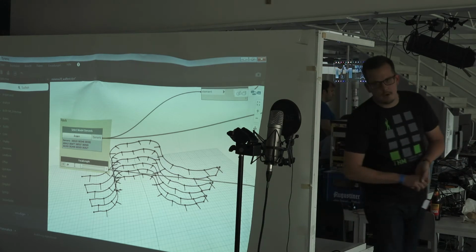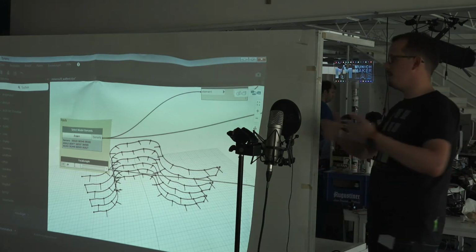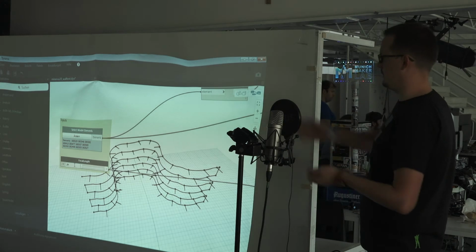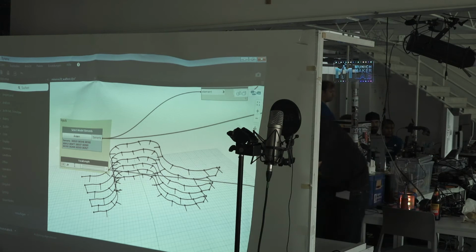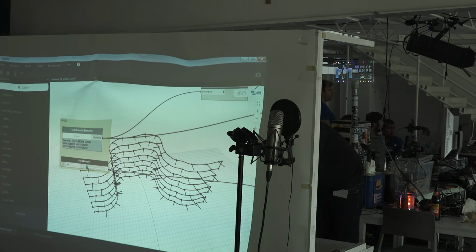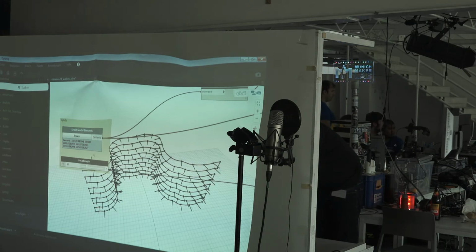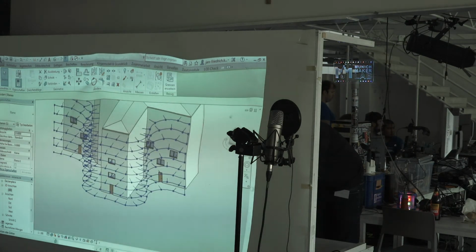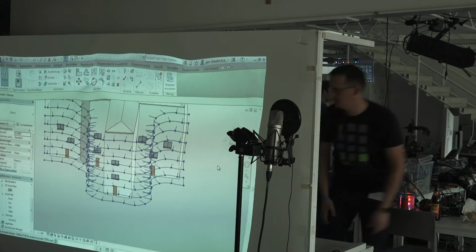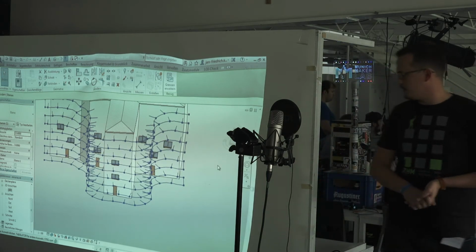You should use about 35 to 50 millimeters for optimal results in photogrammetry. That's what the developers of the software tools say. So you can do that. Then you have to take more photos, but the quality of your model, so the point cloud, which is the result, gets better. So with 45, for example, the recalculation is done. You can see in the model that there are more points, better and 3D. More points, better quality of the resulting model.